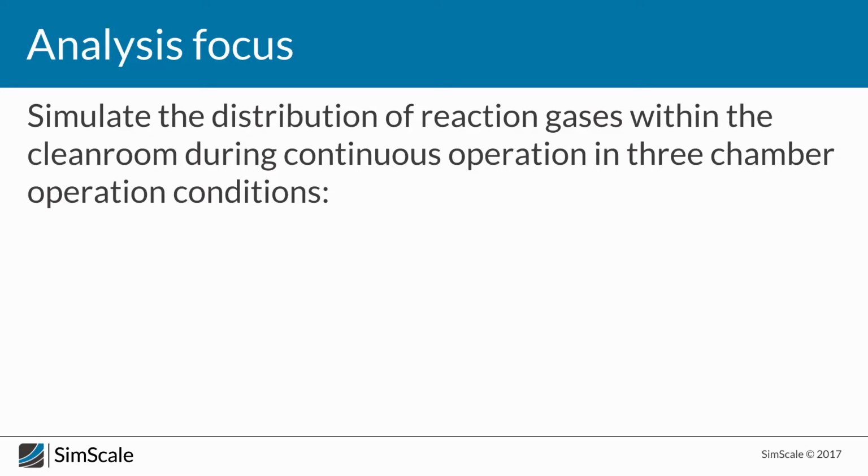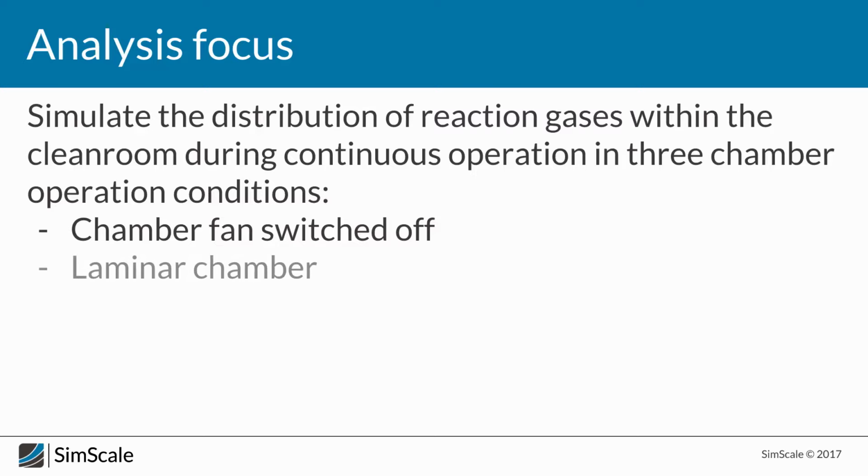In this case, we have three operation conditions. We'll switch off the hood and the fan that is positioned at the top of the reaction chamber. We'll operate the chamber in a laminar way, trying to blow out all the contaminants and the resulting reaction agents. And finally, we'll take a look at different suction chamber conditions, trying to estimate what should be the minimum speed of operation for our chamber in order to not pose any threat